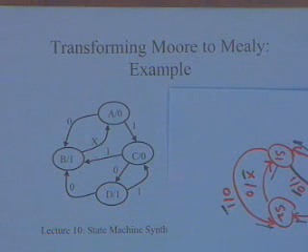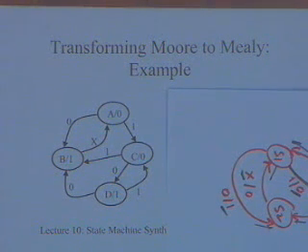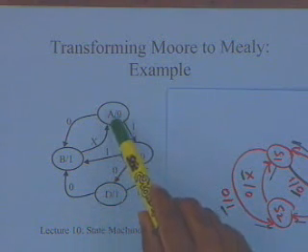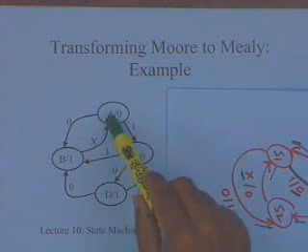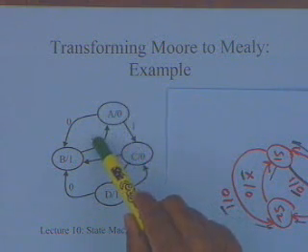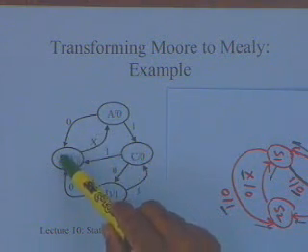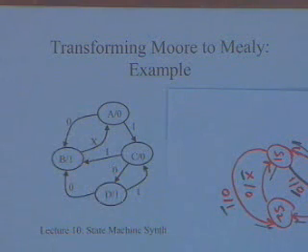Like when you are going from Mealy to Moore, the outputs are getting postponed, because the outputs that are going to be associated with the destination edge, that is where you are incident. So this particular output is going to get moved to this. This particular output is going to get moved to this. So now in the Mealy model, the outputs will go to the edges rather than the states.